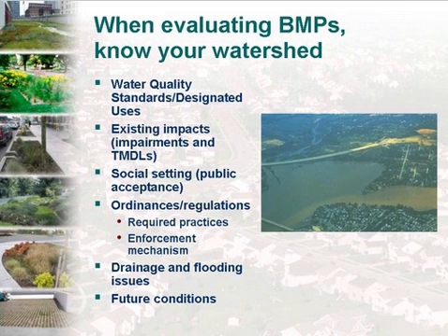Okay, and then another set of considerations that we want to think about is having a better sense of your watershed. Maybe Neely, you can talk to some of these points too. Yeah, it follows up on my previous comment about understanding your local watershed and what you're designing your BMP for. What purpose is this BMP going to serve, to establish this particular set of standards? What type of impacts do I need to account for by reducing flow volumes, or is it a concentration? Is it a combination of those two? Is it a particular type of parameter? What are my pollutants of concern?